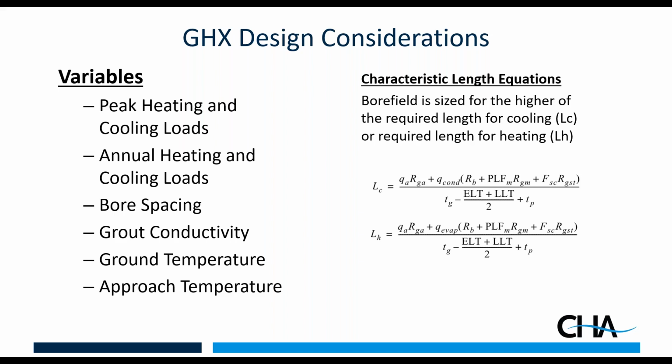Then when we get into what the actual ground heat exchanger characteristics are, we're talking about: what is the spacing in between your vertical bores? What's the conductivity of the grout that's being used to backfill the boreholes? What's my ground temperature? What are my approach temperatures from my HVAC system? There's a lot of variables that go into it. We're not going to get too into all of the nuances because we want to focus mostly on the software, but there are a lot of parameters that you have to take into account.